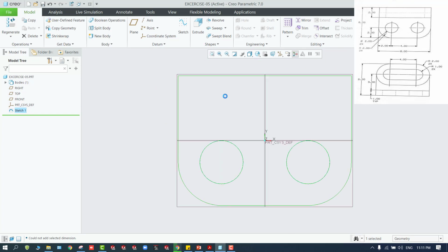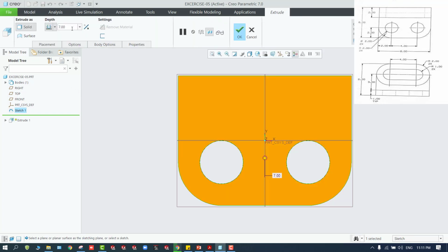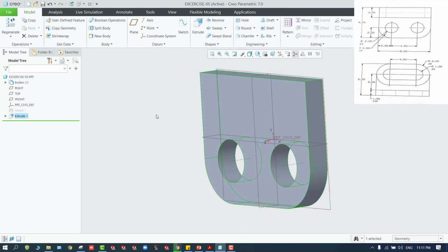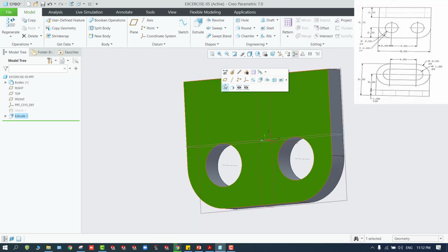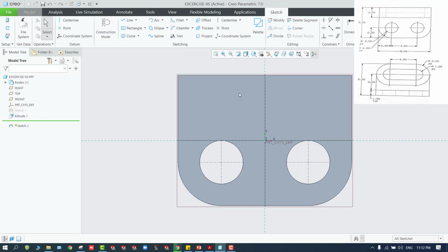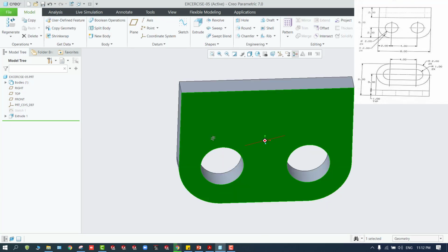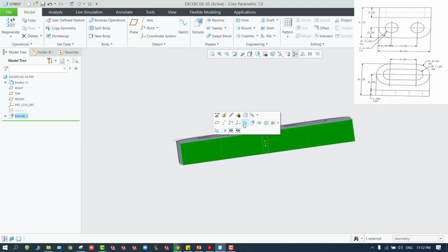extruding this particular stuff. The dimension of this is 1, so you can use extrude up to 1 mm, that is enough. Okay, now on this I need to create the structure. Again, I'll select the top face as a reference on it. I'll sketch. Actually, this is not the face to be considered, so this is the required face.